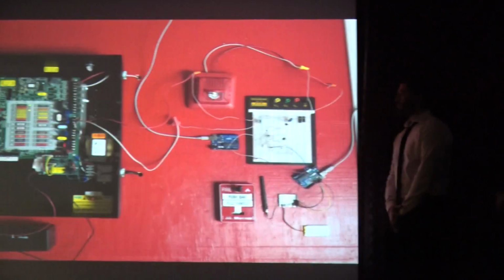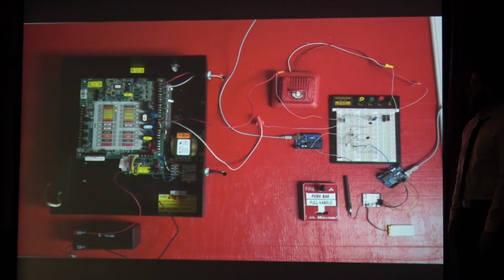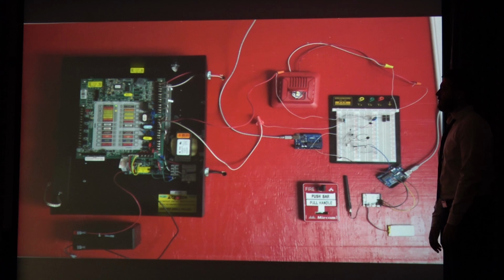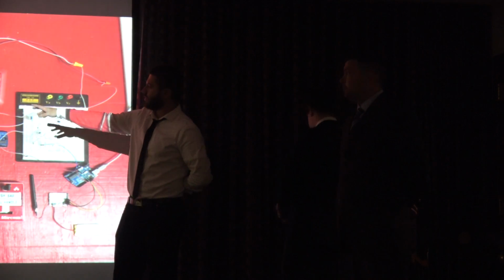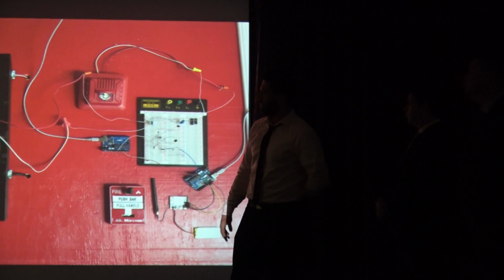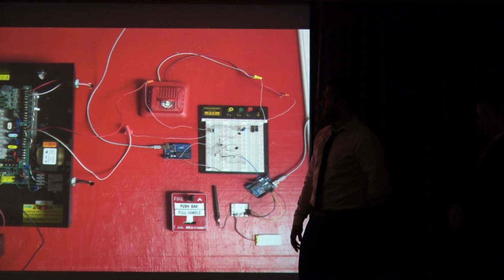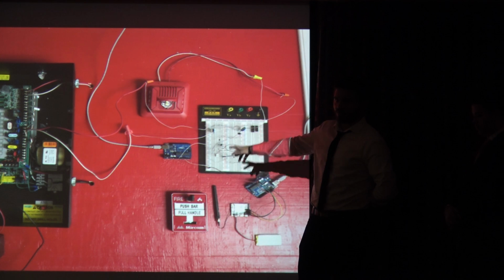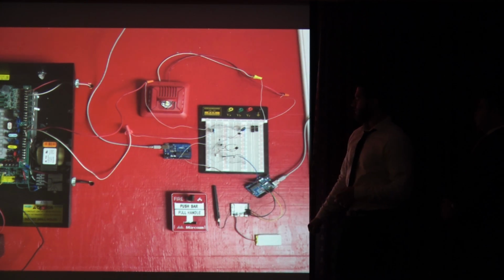To start going over our hardware progress, this is the basic setup of our Inferno system. The left-hand side is our fire panel supplied by Miracom. The top right of our fire panel is what we call the initiation zone. That's connected to the positive and negative terminals of our pull station. The bottom right is our indicating zone, which is connected to the positive and negative terminals of our strobe light. You'll see this more in the demo when you pull down the pull station.